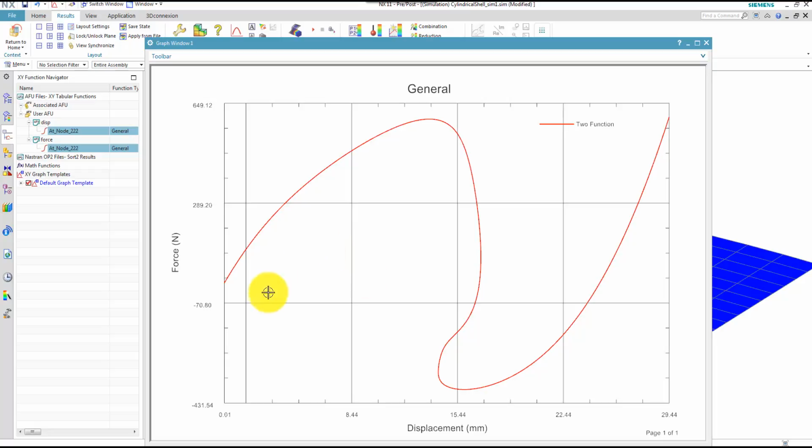You can see that we have been able to capture the nonlinear behavior. We reached a limit point, then the stiffness becomes almost infinite negative, and then we reach the turning point and it snaps back, and suddenly the stiffness becomes infinite high. And then we come to the new limit point, and then again the structure is able to capture the load, and we see an increase.